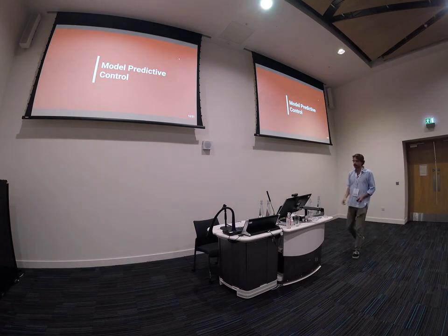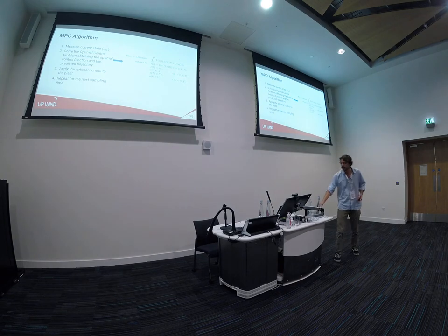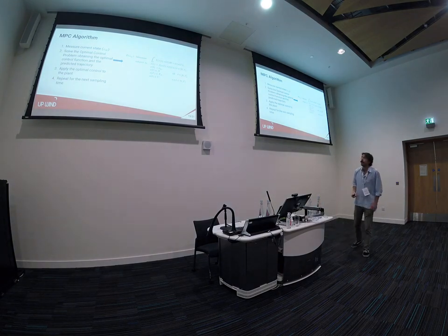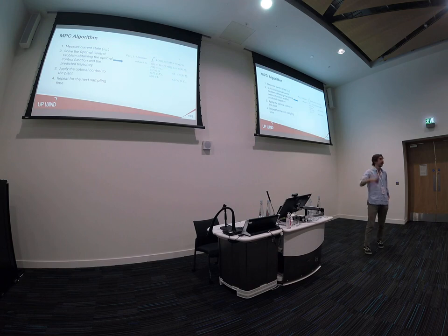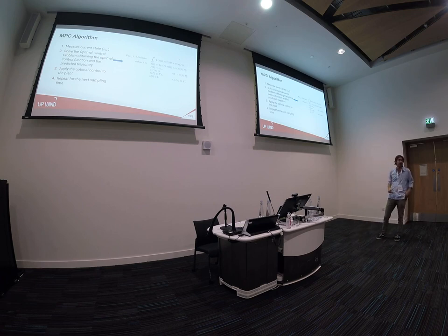Now let's talk about the MPC term. Okay. First of all, I'm going to at least give a brief explanation of what MPC is. Okay. So MPC, this is the algorithm. So basically, we're solving at each time step. We measure the state, and we solve an optimal control problem. This optimal control problem, basically, we optimize for a given cost function. This cost function is basically the one on top. So we have a stage cost L and a terminal cost G.